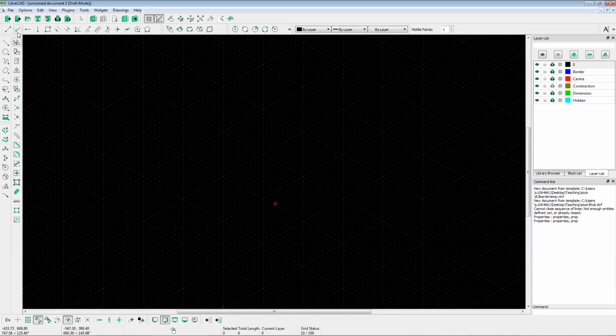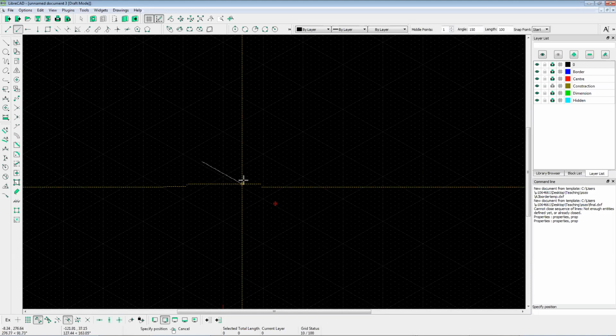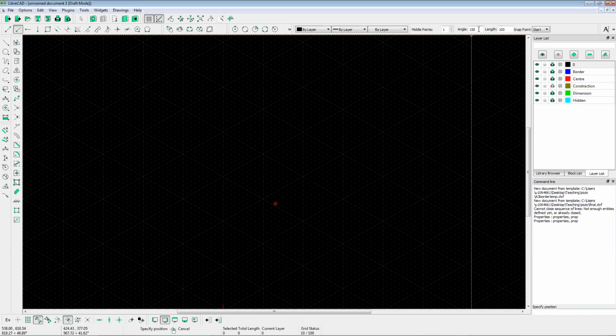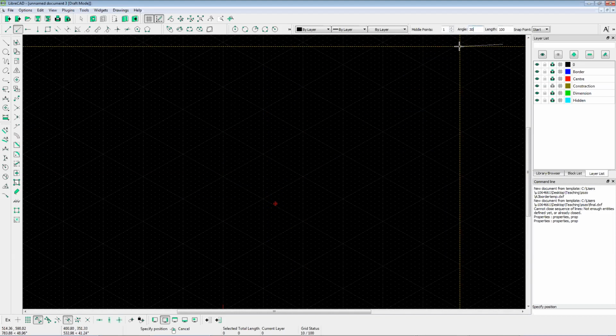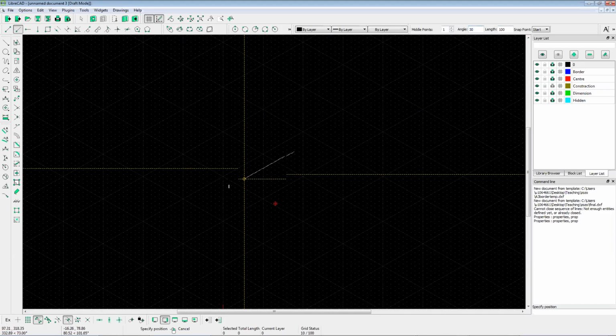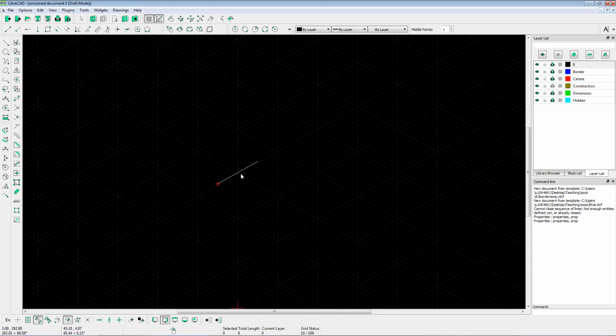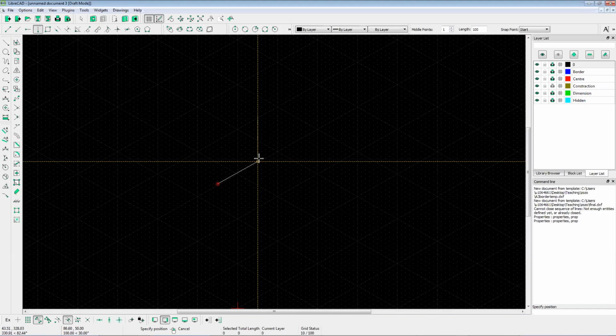To draw a box with the inclined angle, usually we take the options here. We have an option for the angle, we'll just change it to 30, and then the length, which is 100. If I put it anywhere here, I'll get the line inclined at a 30-degree angle. Then I have another line, just a vertical line from this end.